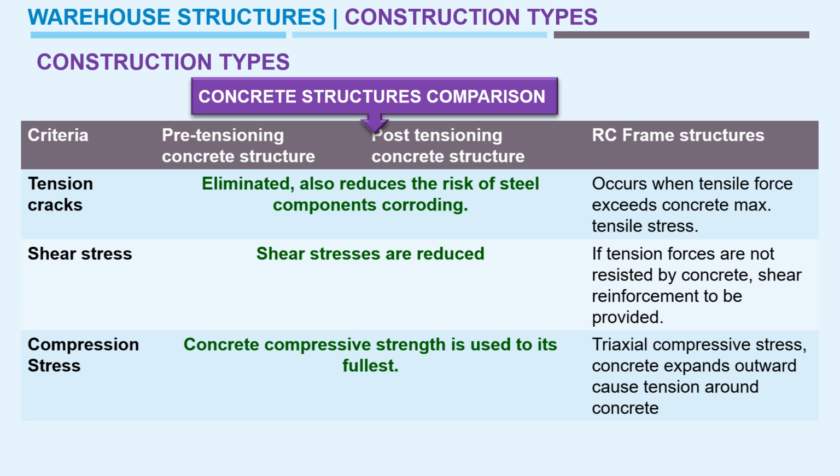Because in two directions for beam members, if we apply axial forces, it will carry the compression stresses. If you apply compressive stress on the beams, it will carry the compressive resistance. With triaxial compression, it means if you apply a force in the z direction as well, instead of only x and y, then there will be an outward tension which will cause damage to the concrete.